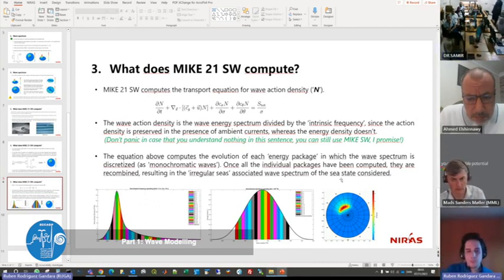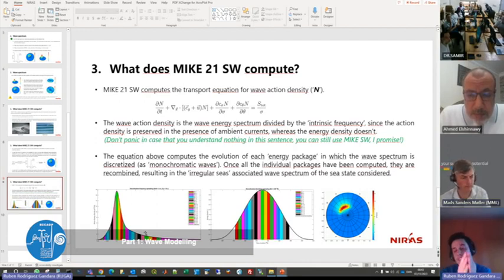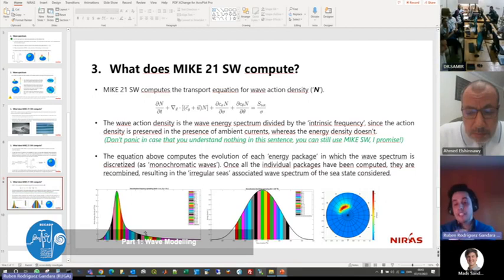He's going to assume a certain theoretical profile or theoretical expression for the energy, which is basically dependent on the frequency. And then regarding the energy, I told you that although you have a mean wave direction, it does not mean that all the energy goes all the time in the same direction. It means that on both sides of that mean direction, you will have some spreading of the energy, because waves have differences of 1 degree, 2 degrees, whatever.